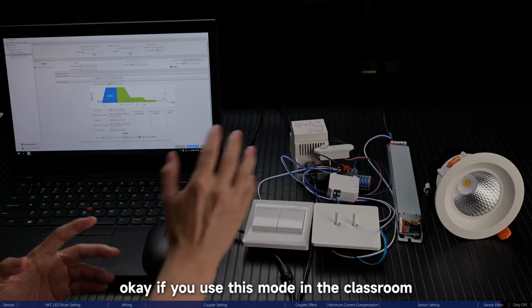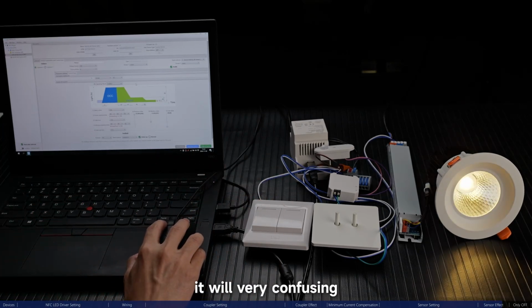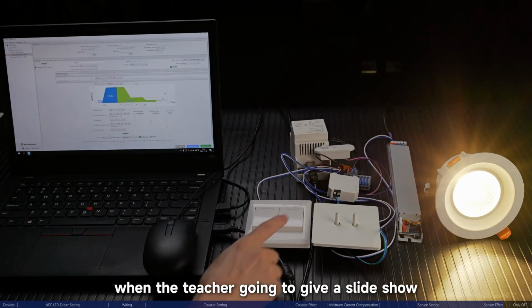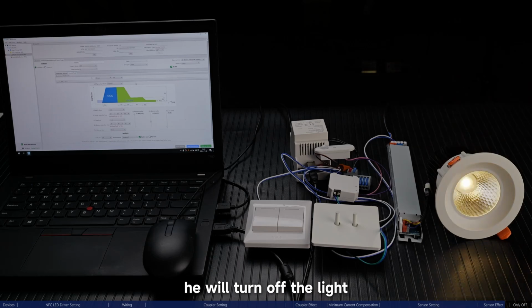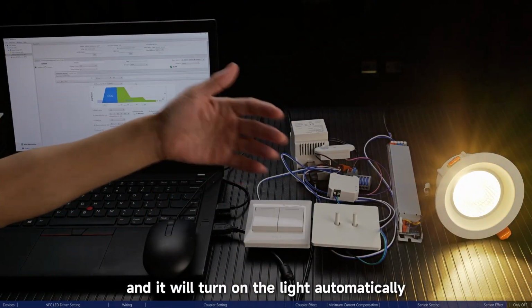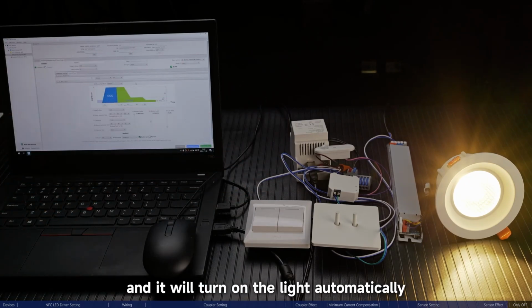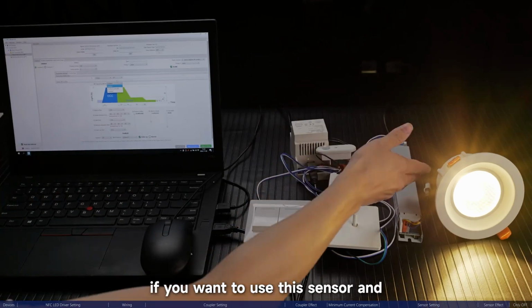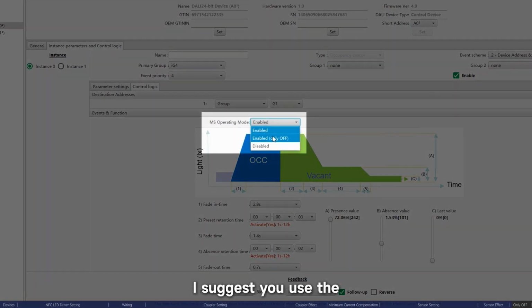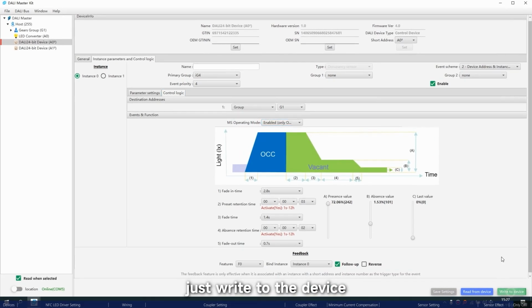Okay, if you use this mode in the classroom, it will be very confusing. When the teacher goes in to give a slide show, it will turn off the light, but the sensor will detect motion and turn on the light automatically, and it's very confusing. If we want to use this sensor and the DALI system in the classroom, I suggest you use the enable only off mode. Just write to the device.